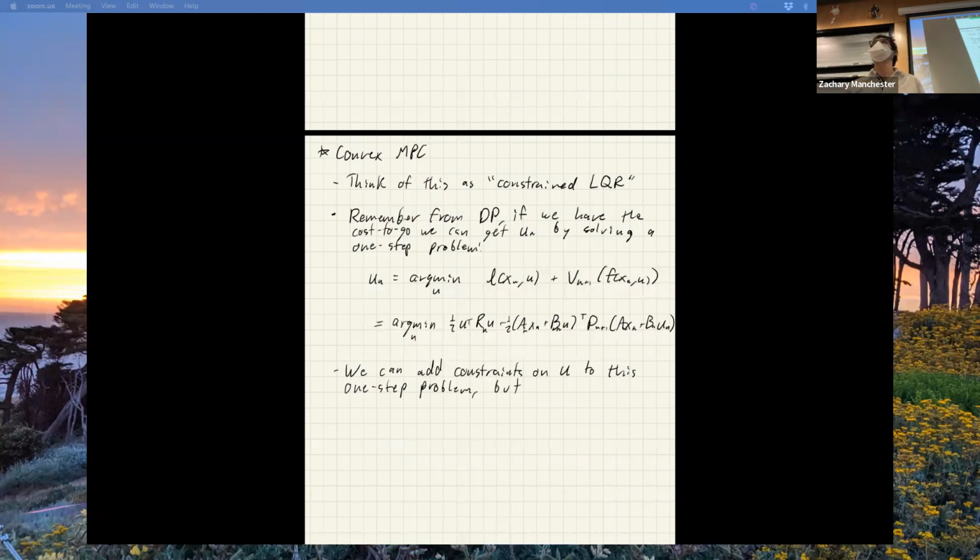Yeah. The cost to go is kind of incorrect, because it's the cost to go for a different policy. Exactly, that's exactly right. The cost to go here from LQR is computed with no constraints, so the cost to go is ignoring all those constraints. So it's totally wrong, basically, out into the far future.